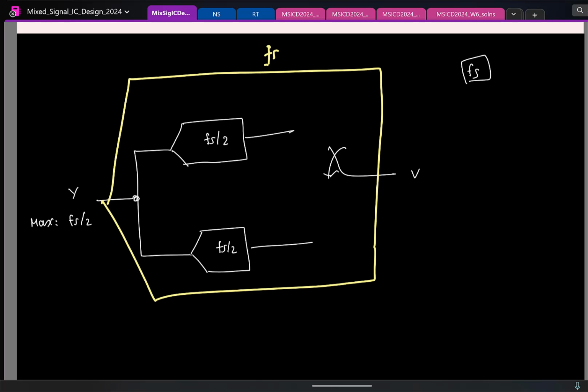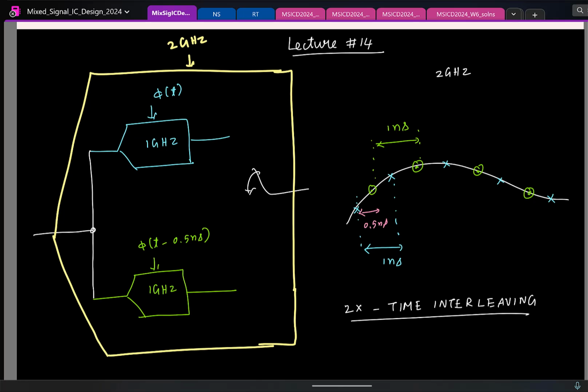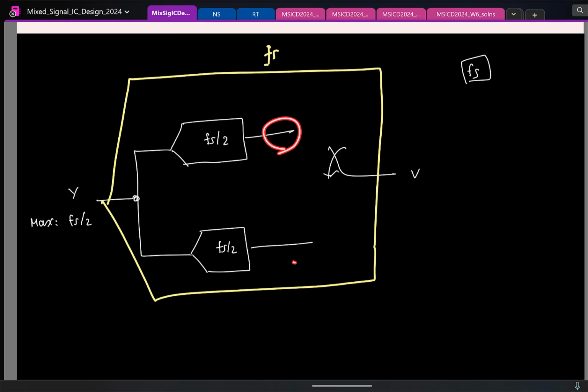So again, this we saw in time domain. We came to this, and in time domain we saw this is foolproof, no monkey business. We need to sample at some sampling period, and we are sampling at that sampling period finally. But it looks like in each individual sub ADC there will be aliasing. So what do you think is happening? Right, the first ADC is missing some information, which will be picked up by the other ADC. Yeah, that's exactly how we saw in time domain.